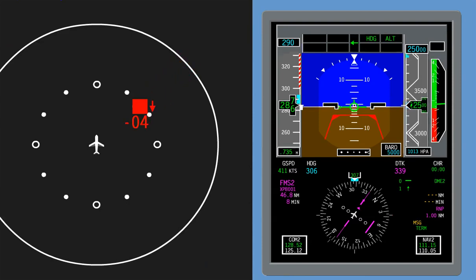When the TCAS detects an RA condition where certain ranges of vertical speed are not recommended, preventive RA, one red trapezoidal avoidance zone is displayed. When the TCAS detects an RA condition and a maneuver is recommended to increase the vertical separation, corrective RA, Descend. Descend. Descend. One or two red trapezoidal avoidance zones and a green rectangular fly-to zone are displayed.